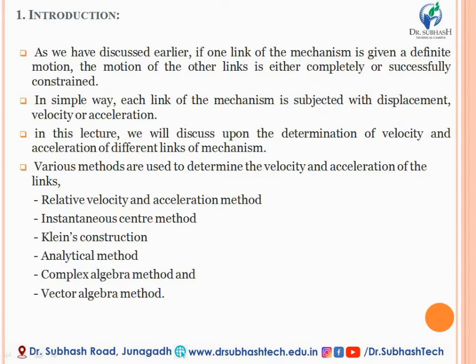There are a number of methods used for the determination of velocity and acceleration of the various links of the mechanism, like the relative velocity and acceleration method, instantaneous center method, plane construction, analytical method, complex algebra method, and vector algebra method. So there are these 6 kinds of methods or procedures through which you can calculate the velocity and acceleration of various links.